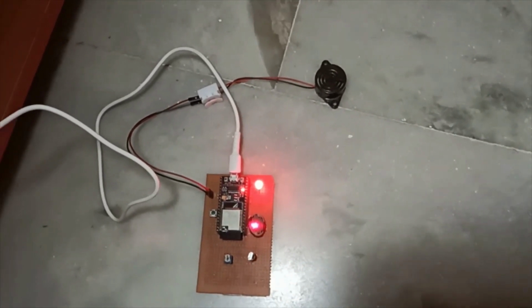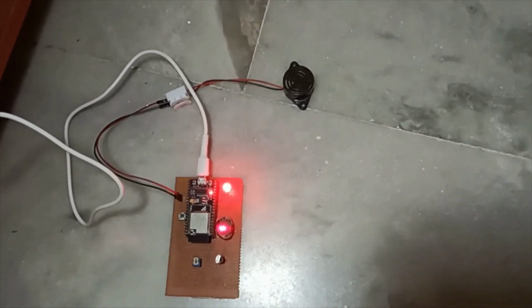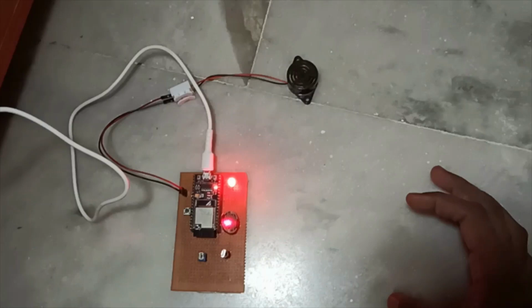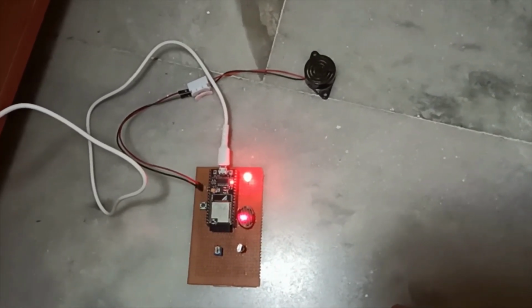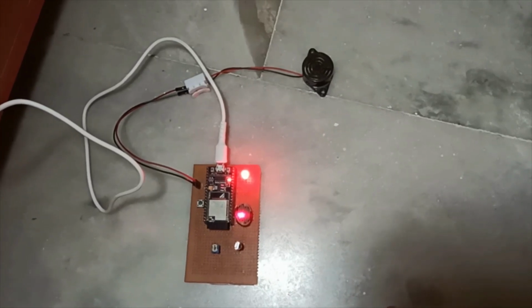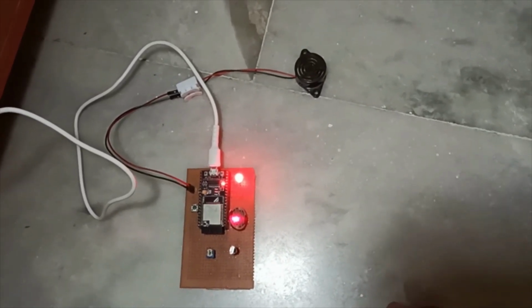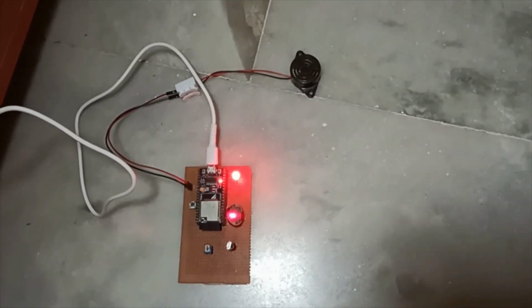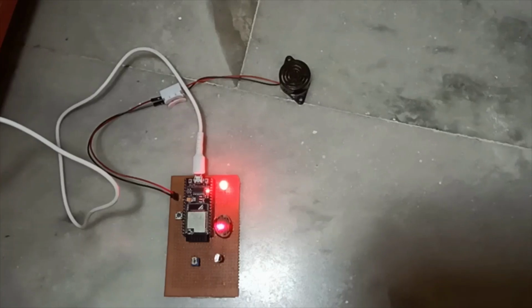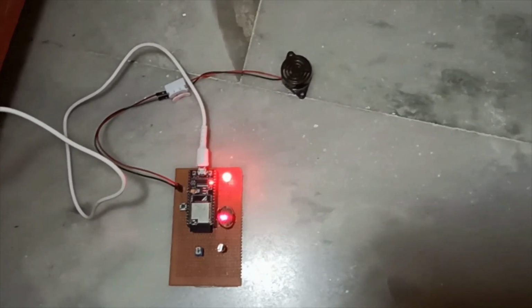We can control the state of the alarm using the Blynk IoT app. Not only will the ESP32 trigger the alarm and send the state to the Blynk IoT app, it will also trigger a webhook service by which we get an SMS on our mobile phone. We have to specify the mobile phone number to get the SMS. That is made possible using the IFTTT app.